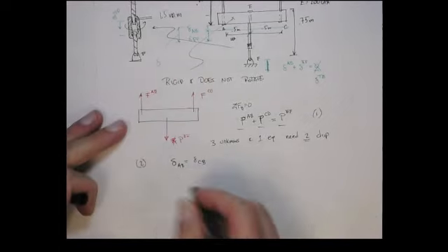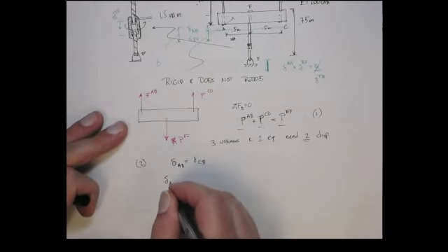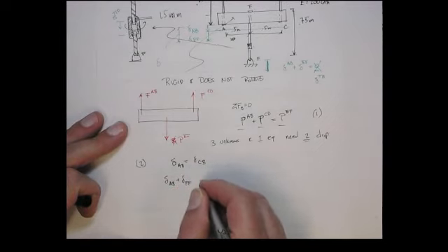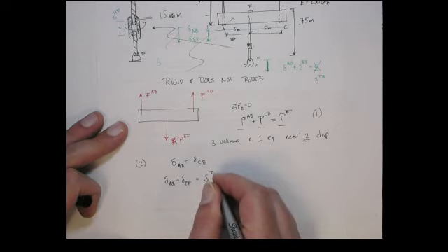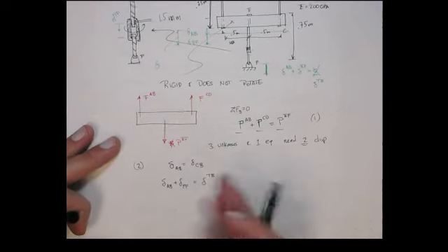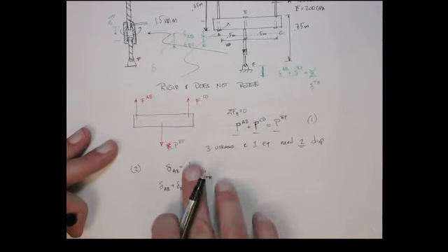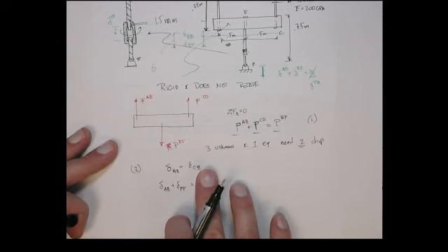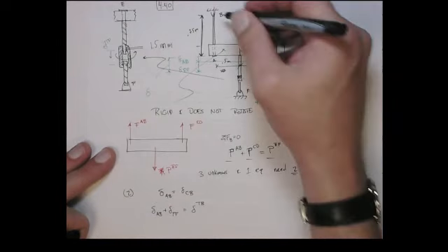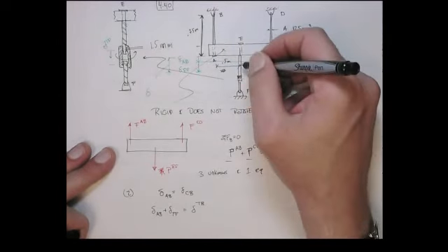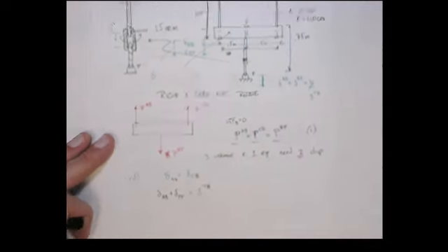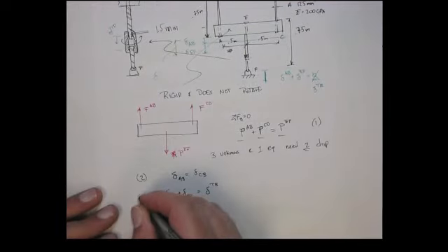It's a little difficult to draw, but the elongation of AB plus the elongation of EF equals the elongation of the turnbuckle, or the delta change at the turnbuckle. This is the two threads coming together. So if there was no turnbuckle, this would go to 0, right? And then you get the regular compatibility. Whatever AB increases in length, EF has to decrease, or vice versa. Whatever EF increases by, AB has to decrease by. Okay? So this is the third compatibility equation.